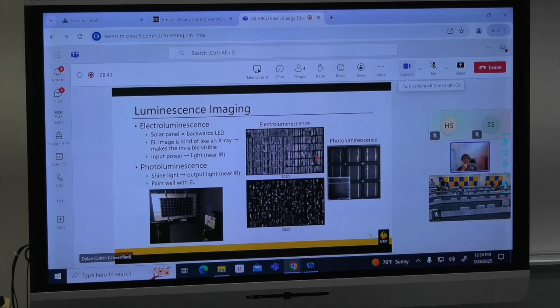So all of these, this contact corrosion. On the cells, they're called bus bars, and you can see them here. Those are the main metal contacts that are extracting most of the current and transferring it. So you can see those contacts corroding.